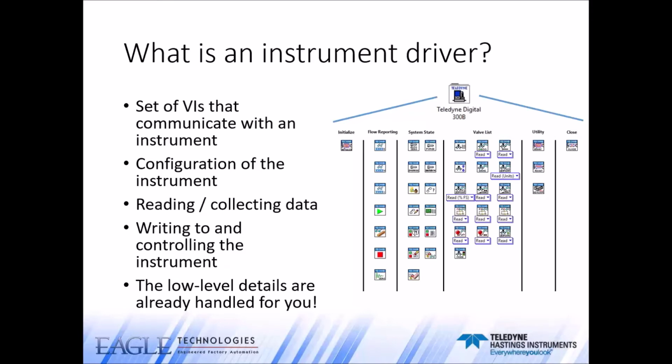An instrument driver provides the interface between the core LabVIEW software and the instrument or device that needs to be controlled or monitored. The LabVIEW instrument driver is, essentially, a set of software routines that facilitate data exchange with the instrument or device. Within the overall driver, there are individual functions that perform specific tasks. For example, configuring the device, reading from, writing to, and triggering the device or instrument.